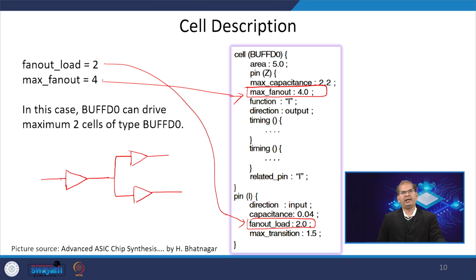So, if I have a requirement of driving more than 2 buffer cells, then I need to modify this buffer cell, because this buffer cannot drive more than 2 buffers of the same type. This kind of analysis will be done by the tool.